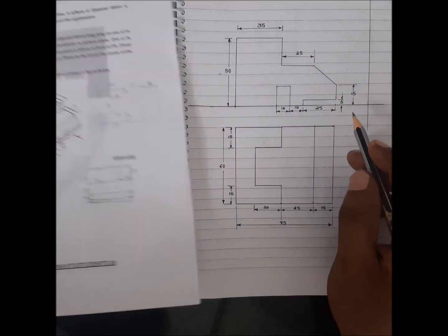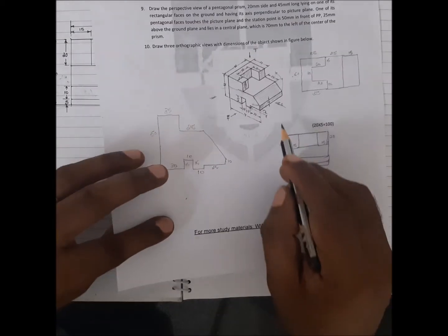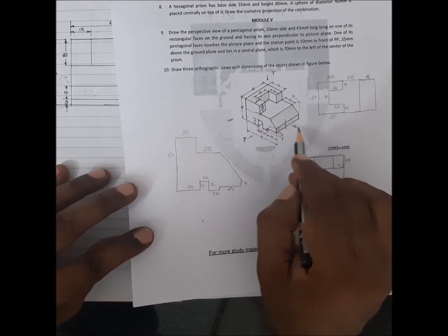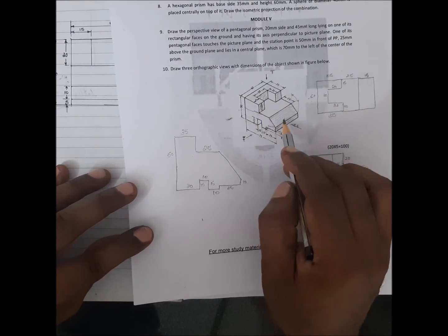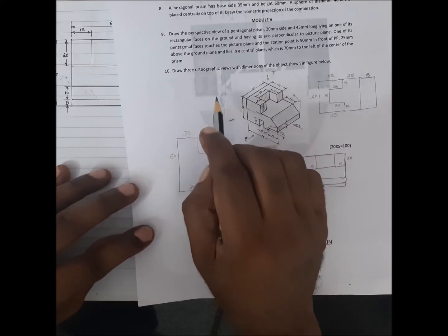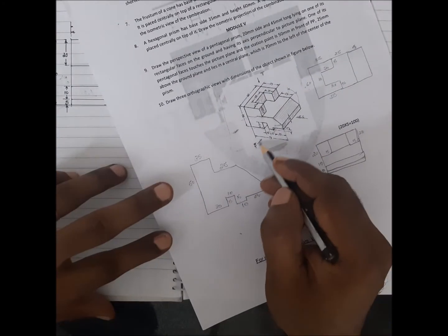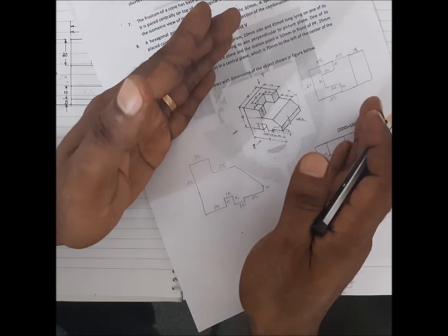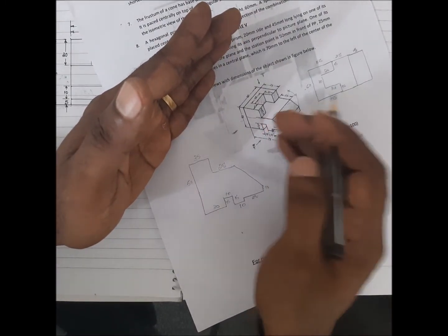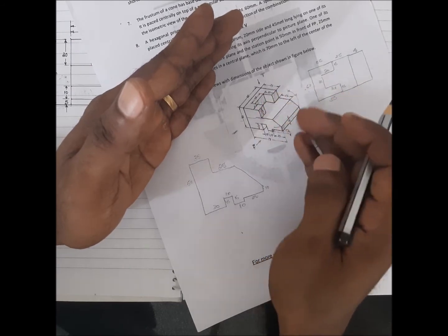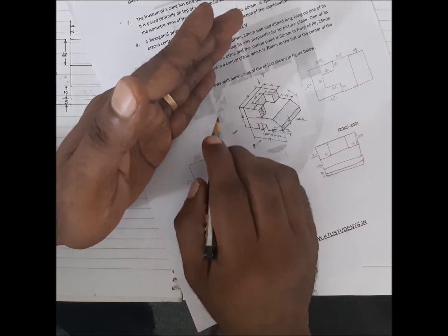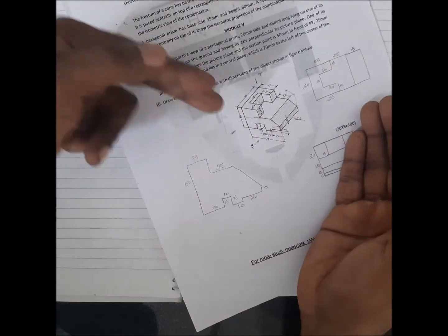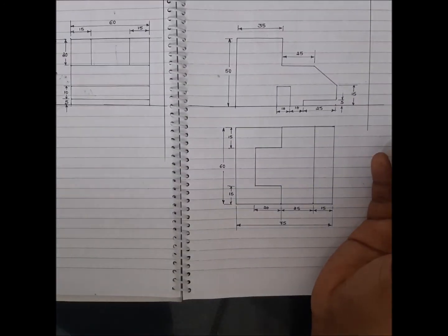The point you have to notice is that when you draw a side view, when you look at the object in this direction, whatever you see is drawn at the left side. So this is your front view, this is the right side, and this is your left side of the object. So when you look at an object from the right side, the image obtained is drawn on the left side, whereas if you look at the object from the left side, the image obtained is drawn on the right side. So that is the essence of first angle projection.